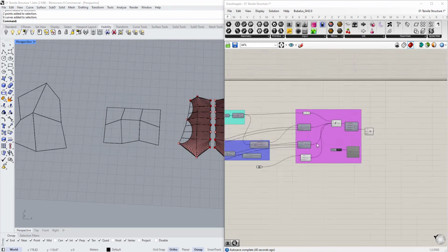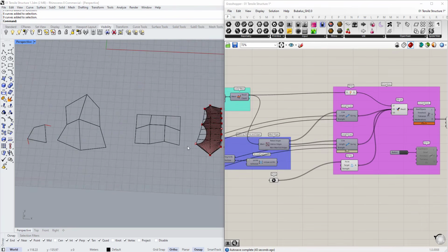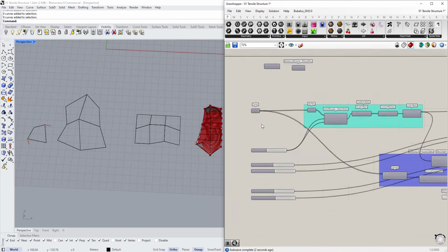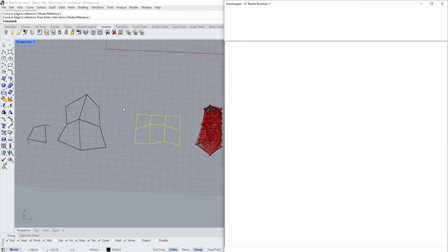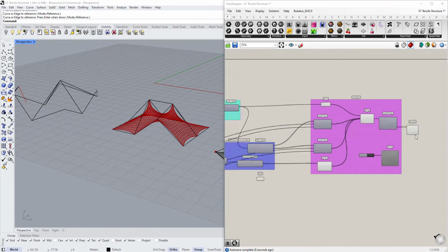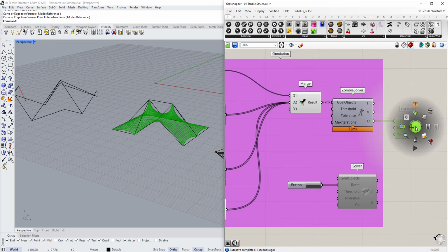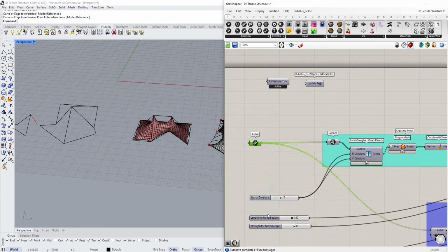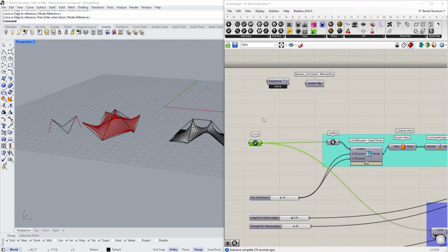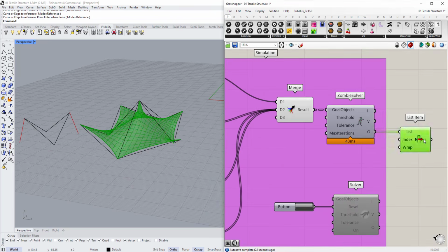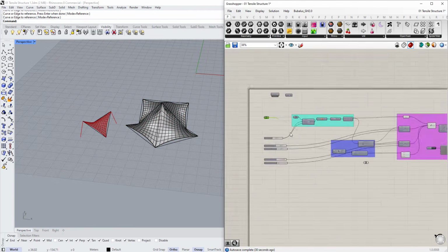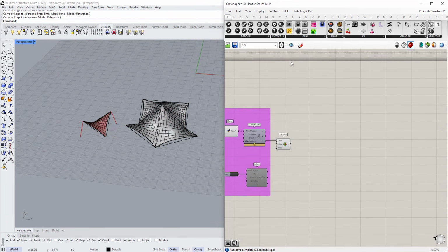And for the remaining structure, I'm going to use this method. I'm going to place this like this, and I will come here, set multi curves and select all of these curves. We'll have our structure, and I'm going to pick it. You can come here and click the mouse middle button and pick it, and the same thing for the remaining. You can come here, set multi curves. See, we are generating very complex surfaces in literally no time. Come here, click the mouse middle button and click here again, set one, set this one, click the mouse middle button and pick it.